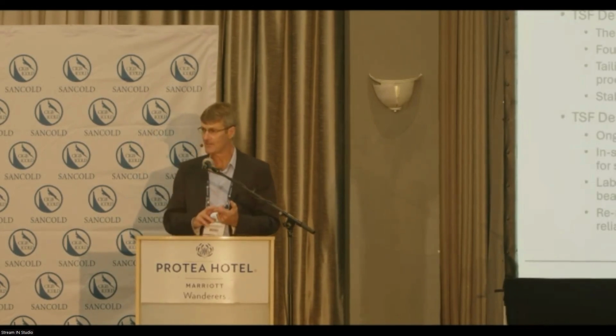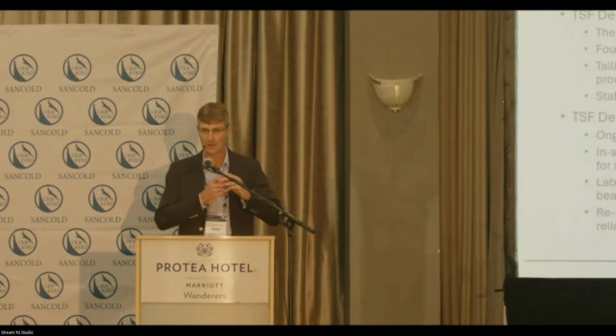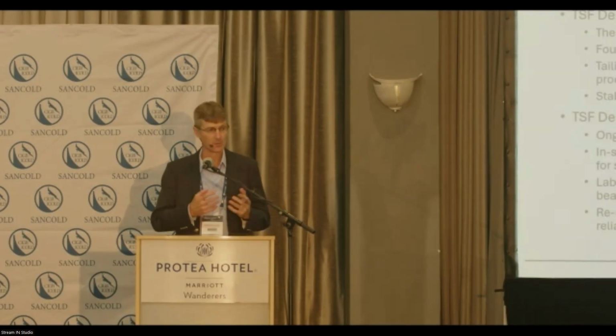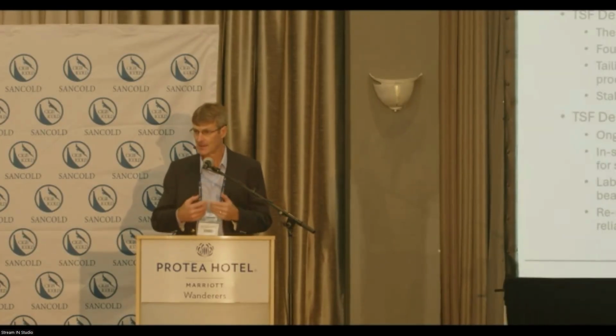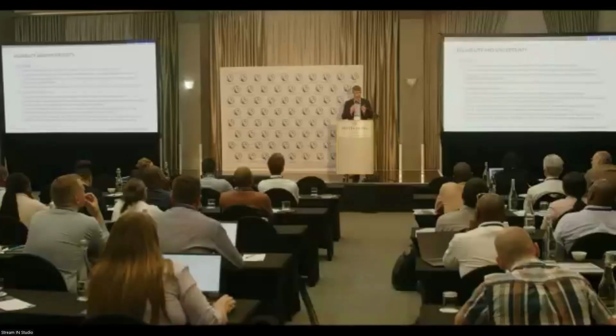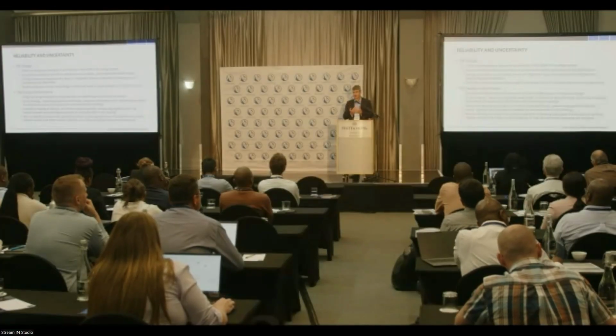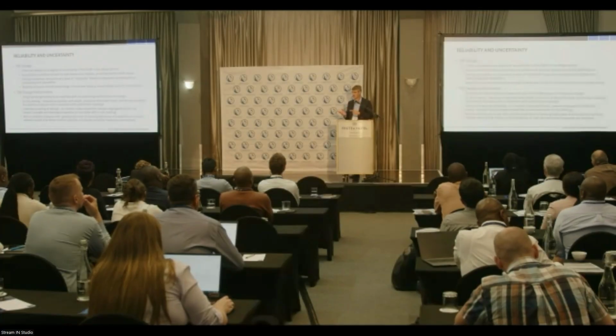So how do we get that information? Now we should be in a position where we're asking for enough testing that we've got sufficient triaxial tests that we've got critical state lines, that maybe we're taking into account cyclic shear testing as well. So whatever it is that's related to your structure, you should be getting sufficient information that you've got reliable information and you can produce a robust design. And the same with the in situ testing.